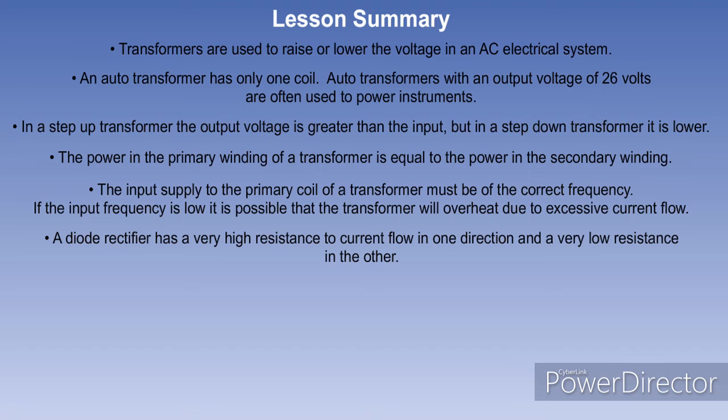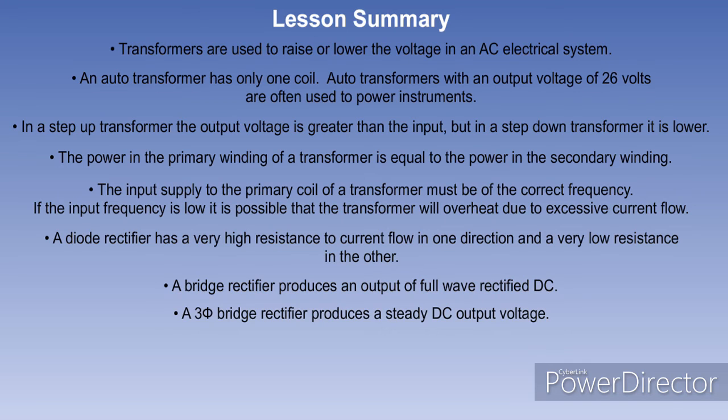A diode rectifier has a very high resistance to current flow in one direction and a very low resistance in the other. A bridge rectifier produces an output of full-wave rectified DC. A three-phase bridge rectifier produces a steady DC output voltage.